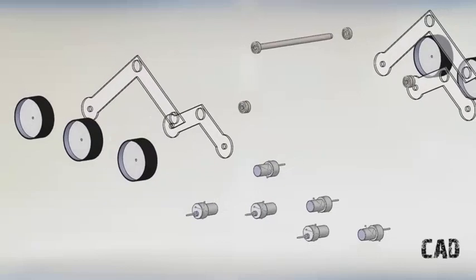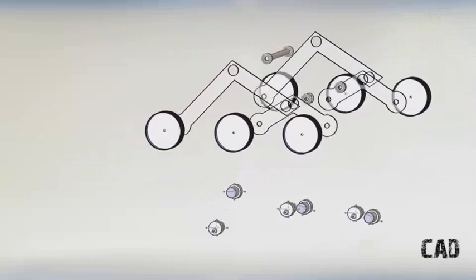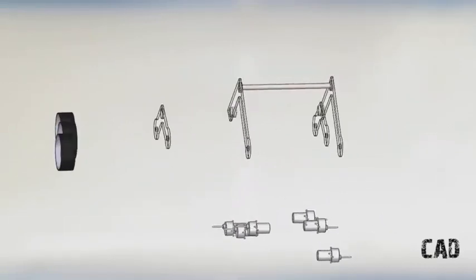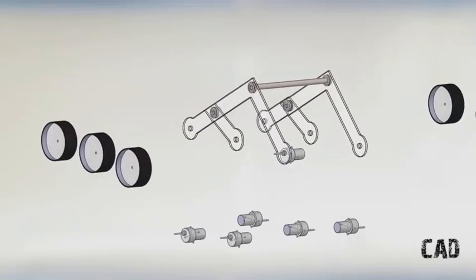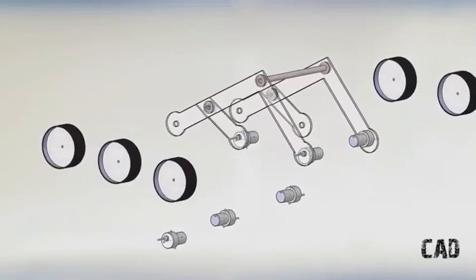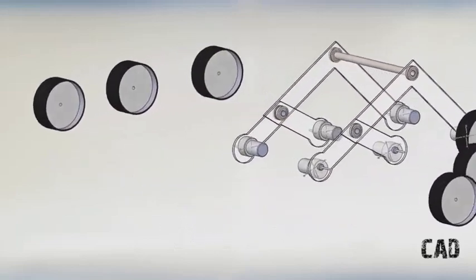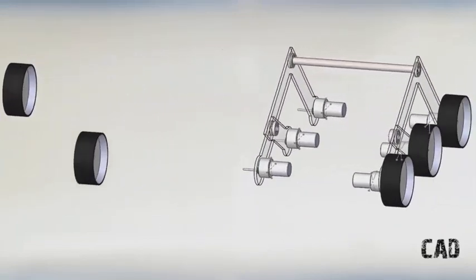The rocker part of the suspension comes from the rocking aspect of the linkage on each side of the rover. These rockers are connected to each other and the vehicle chassis through a differential. The chassis maintains the average pitch angle of both rockers. One end of a rocker is fitted with a drive wheel, and the other end is pivoted to the bogie.